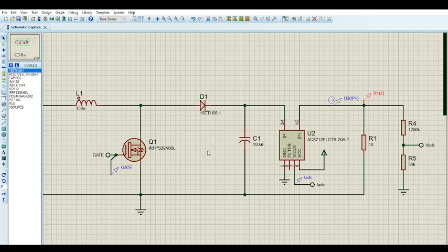And like I said, usually when you calculate the voltage and current values for these converters, when you calculate the capacitor values and the inductor values, they are usually low for high frequency converters. And sometimes with the capacitor, you might get a value of say 5 microfarads or 3 microfarads. And I know the original thought is, oh my gosh, that's so low. No, it's not. It's actually a good value. If you're gonna increase that value, try not to go more than 3 to 4 times of that value, because once you go past that, then you might have issues, especially in a case where you have a continuous current load. If it's a continuous current load, it's fine, believe me.